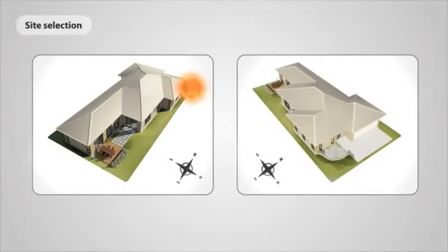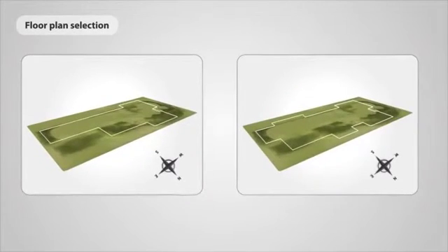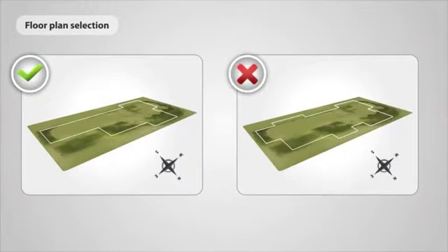Avoid long blocks that run north-south, as they make it harder to achieve a 6-star standard. Try to pick a block where you can have your living areas facing towards north on the block. By reducing the amount of wall area, you decrease the amount of inside space in contact with the walls, and this minimises the loss of heat and makes the home easier to heat and cool.